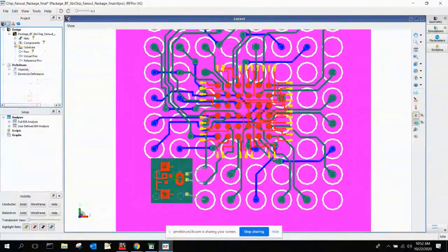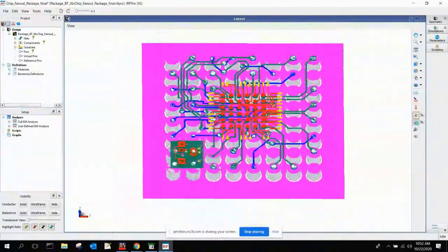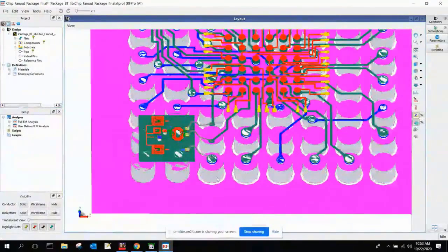Well, the next thing that you may be interested in doing is, in a lot of cases for boards, we have vias, right? So we treat the balls as vias, but they're not actually 3D components. So one of the new capabilities in the tool is the ability to go and remove some of these vias from the mesh and replace them with real 3D components. So that's what I can do here.